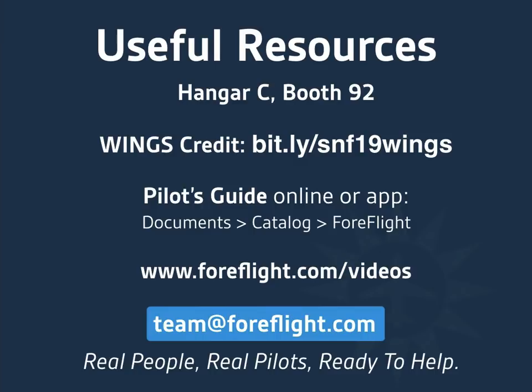Is there a way when you're looking at ADS-B traffic that you can mask traffic that's like 30,000 feet above you? Is it selectable? How do you do that? Let's say that I'm looking at traffic on the map view, and I don't care about traffic that's far away or way above me. Can I hide that? Yes. There is a setting in the More tab under the Settings view. It's called Hide Distant Traffic. That will get rid of anything that's not close to you. It's not configurable for altitudes right now.